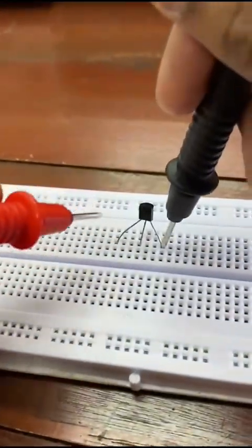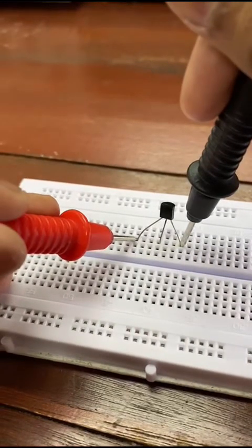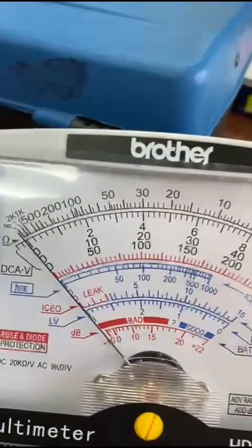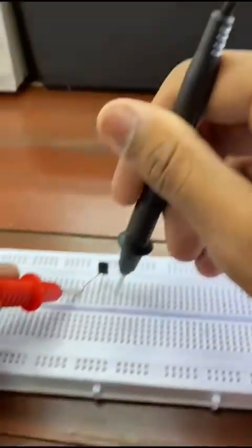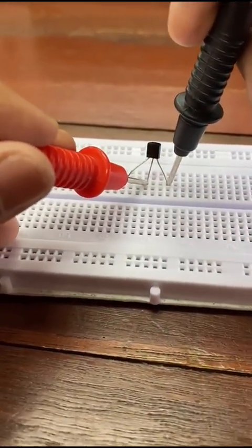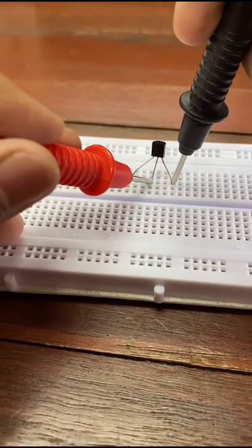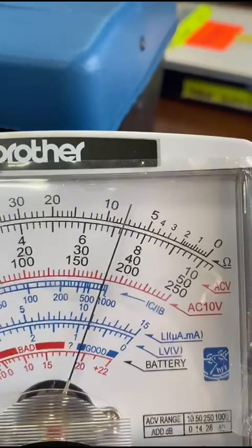Then I put the red probe on terminal 1 and the black probe on the same leg, terminal 3. The result shown on the multimeter is the same as the first experiment that I did. It also gives infinity ohm. And for the last experiment, I change the red probe to terminal 2, and the black probe is on the same leg, terminal 3. The result shows 75 ohm, like experiments 3 and 4.